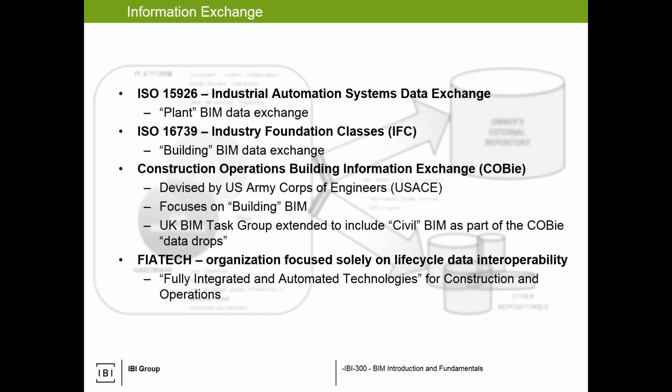So those are two standards that are built, one to bridge the plant tools or bridge the building tools, and owners are understanding that and saying that they can accept information pertaining or governed by those standards. So if I'm in Revit, for example, export to IFC, I get this IFC file, turn it over, that can be taken in by an owner if that's what they're prescribing.